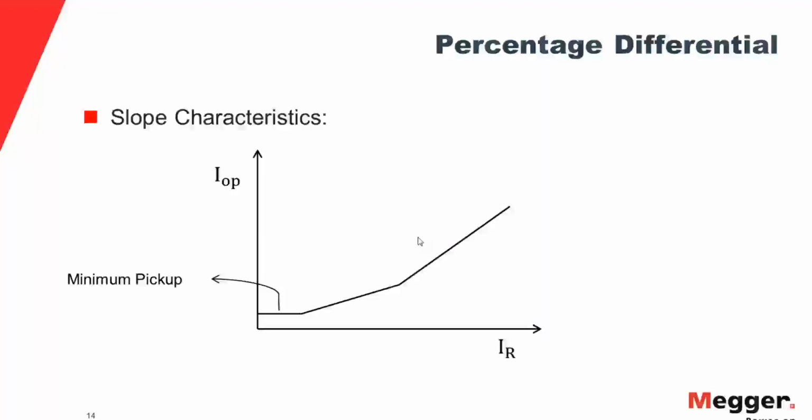So what I do is I disable the distance function tripping the relay. So I am masking the effect of distance function when I am testing the overcurrent function. So that is called masking. So you are not allowing a certain protection function to operate when you're testing a different element. So that is what I talked about, element testing versus scheme testing.